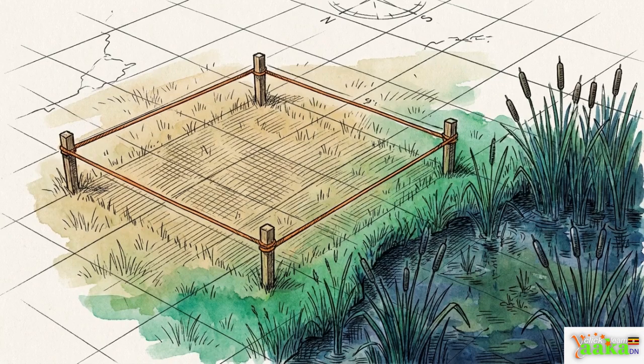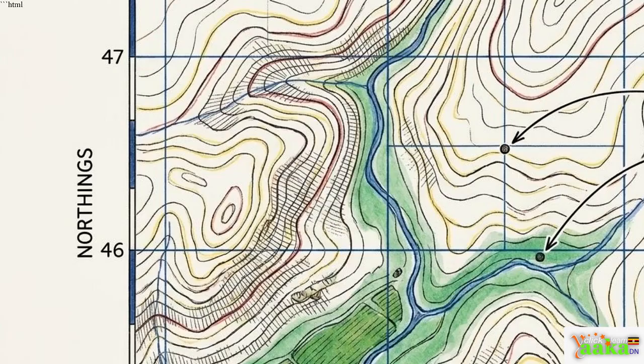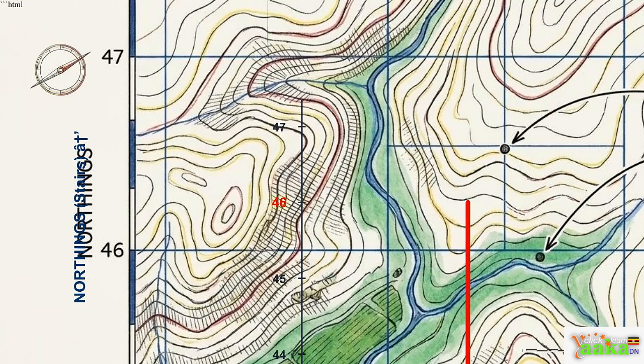We need to claim a specific plot of land for the market that is guaranteed to be safe from the nearby swamp. To find that safe zone, we look at this grid. Notice how a network of intersecting blue lines acts as a targeting mechanism over the terrain, with numbered axes running along the sides. To read these coordinates, we use a simple rule. Run along the corridor, then climb the stairs. That means you always read the horizontal numbers at the bottom first, the eastings. Then you read the vertical numbers going up the side, the northings. By combining the 2 easting numbers with the 2 northing numbers, we get a 4-figure grid reference.